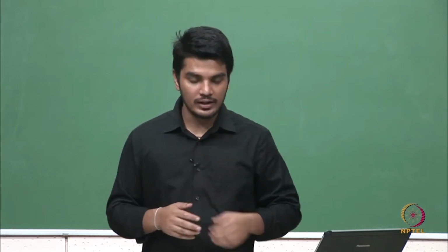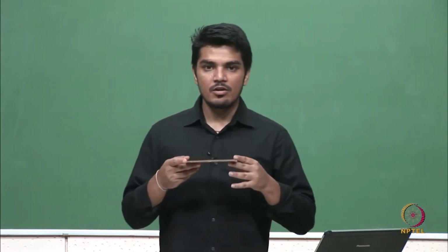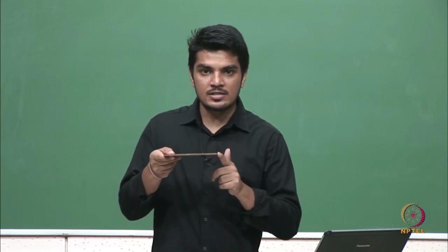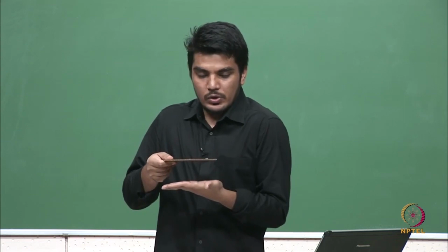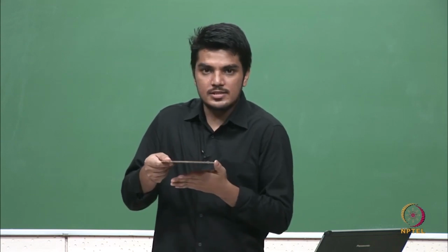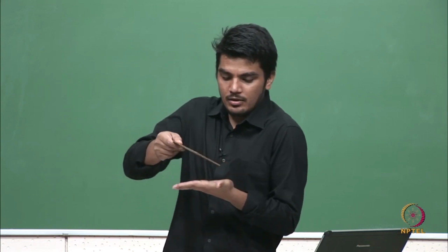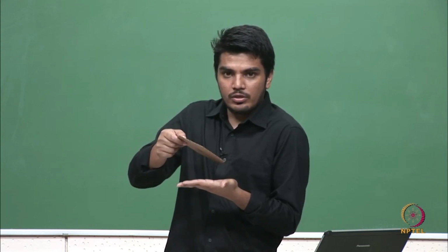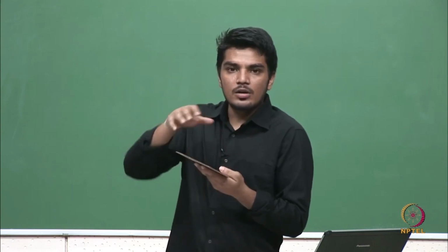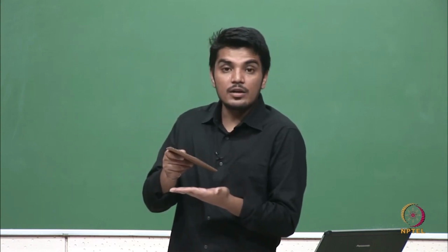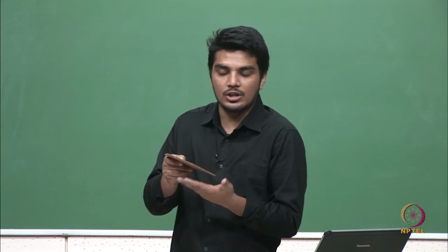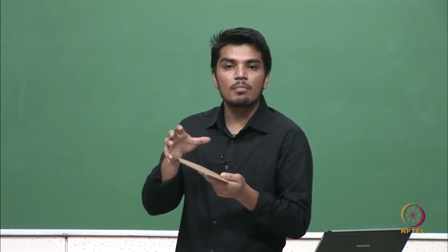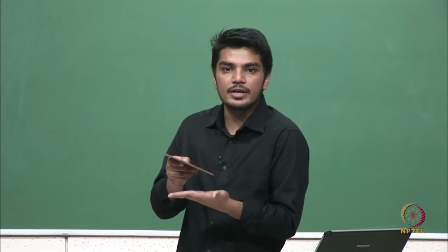Now, moving to the second orientation. In this we have this regular hexagon. This hexagon is rotated about this axis to a 30-degree angle. The first orientation is this. Now, rotating about this axis to a 30-degree angle, we get this. This is the second orientation, and for this orientation, on seeing from top, the shape of the hexagon we obtain is not the same as that in the first orientation, but on seeing from front, we will get the same straight line of the same length, but now it is oriented at a 30-degree angle.